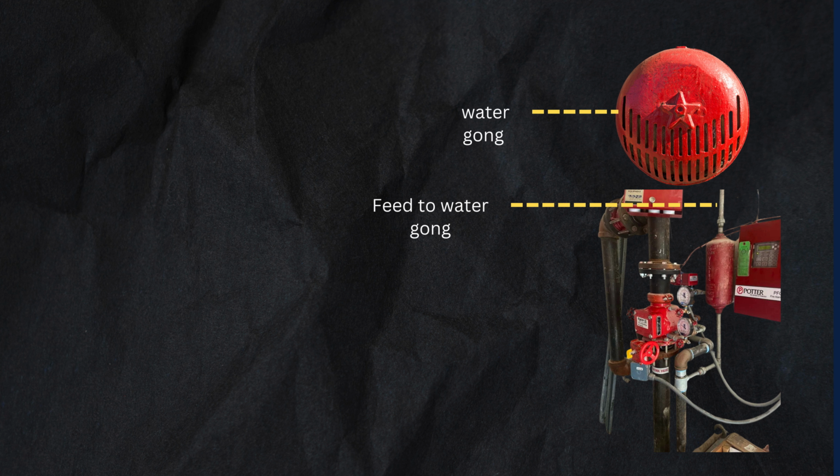Outdoor water motor-operated or electrically operated bells shall be weatherproofed and guarded. All piping to water motor-operated devices shall be galvanized steel, brass, copper, or other approved metallic corrosion-resistant material of not less than 3/4 inch nominal pipe size.